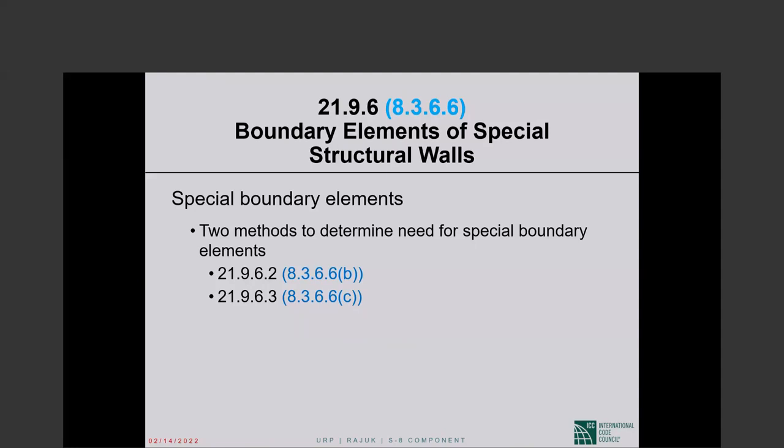A shear wall section that may be 30 foot long, are you going to tie and cross tie the entire 30 foot long cross section like it is a column cross section?